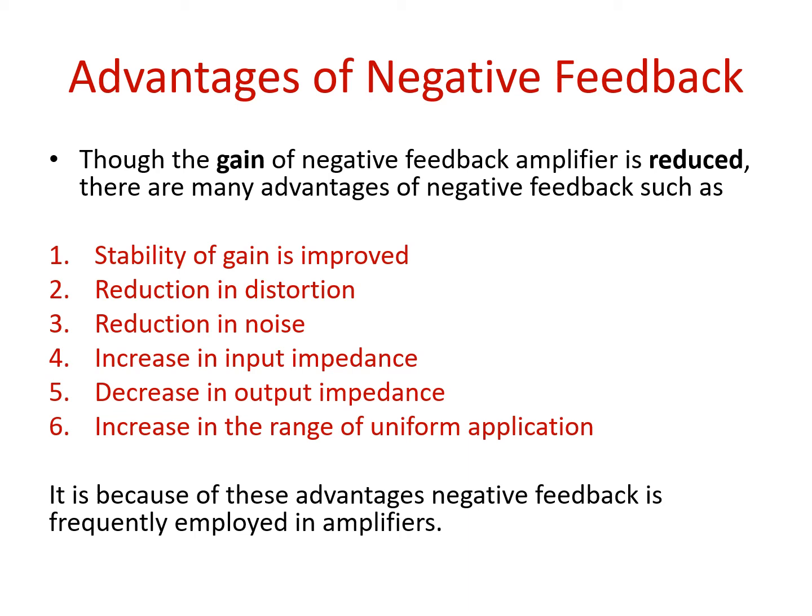Then the third one is reduction in the noise. Whatever noise is introduced during the process of amplification is much more reduced in negative feedback as compared to positive feedback. Then the fourth advantage of negative feedback is that it increases the input impedance. The fifth one is that it decreases the output impedance.